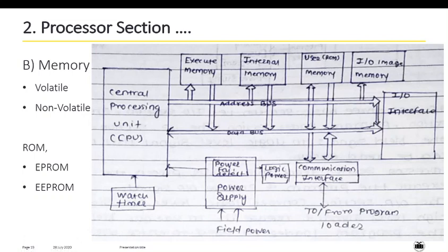In a PLC, we generally use battery-backed CMOS RAM. It is a volatile memory and it consumes a very small amount of power as it is made of CMOS. The space required and power required are very little. The batteries used retain the data during power loss, and the batteries can be replaced after some 6 months to years. So this is the RAM which we use in the PLC.